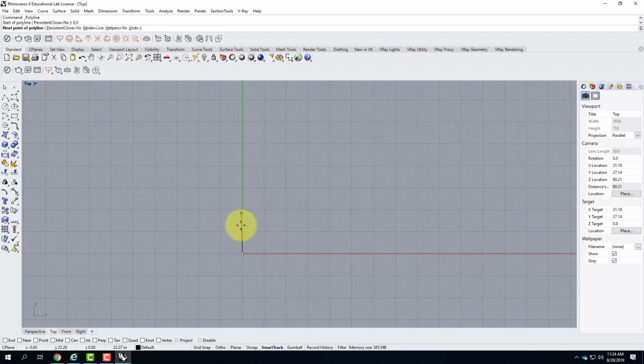At this point, I want to draw a line going vertically right up here at 24 feet long. I'm going to do that by typing the coordinate of where the end point of this line would be. In that case, I'm again working with x first, comma, y. In this scenario, it would be x equals 0, because I want it not to go anywhere in the x direction, but I want it to be 24 feet long in the y direction. So I would type in 0, comma, 24, and then I'm going to put the apostrophe after it for a foot mark. The apostrophe is representative of feet.